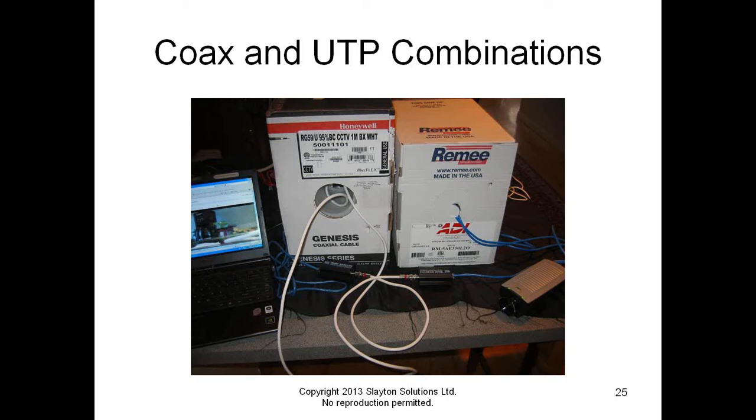This gives us also the ability, it's not just going out to the end of the coax, but we also can extend from there using Cat5e UTP cable. We've got another 100 meters or 328 feet that we can go from the NVT or the Veracity or whoever the manufacturer is. We can go from their interface transceiver out to the remote IP device or the network switch, if that's what you want to put out there. You've got another 328 feet.